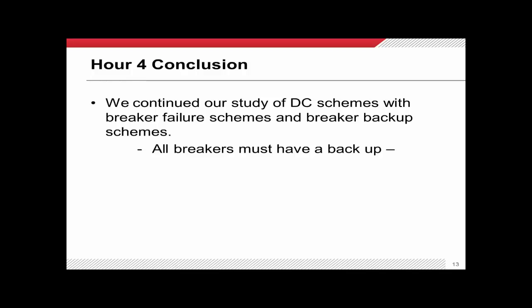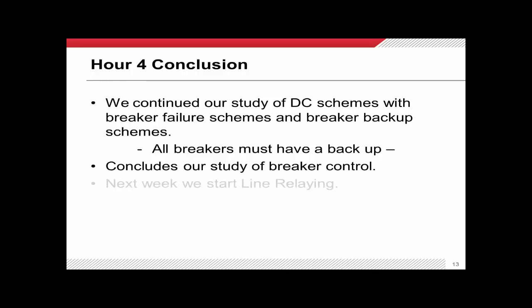All circuit breakers on the transmission system have to have a backup plan, and on the transmission system we refer to that as breaker failure relaying. In fact, all circuit breakers in general have to have backup, not just the big fancy high voltage ones. So this concludes our study of breaker control, and in the next class we will start studying line relaying.